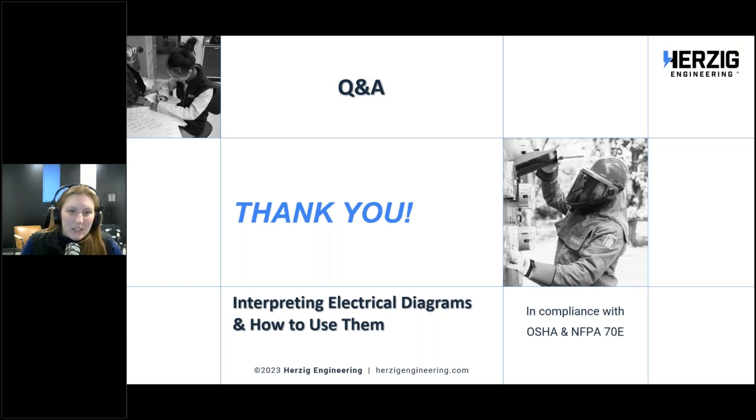All right, got another question here. Use this information to review, determine how much change for renovations, where our drawings have not been fully updated to reflect new connections. Last study was more than 11 years ago. Yeah, see that is long enough that we would typically say just recollect it. If you have one-line diagrams to work with, fine, but most of the time, I mean, 11 years is a long time to go without updates. And I can bet that there's a lot of things that have changed, especially if you've got new connections to switch gears and transformers. That's going to have a huge impact to your study.